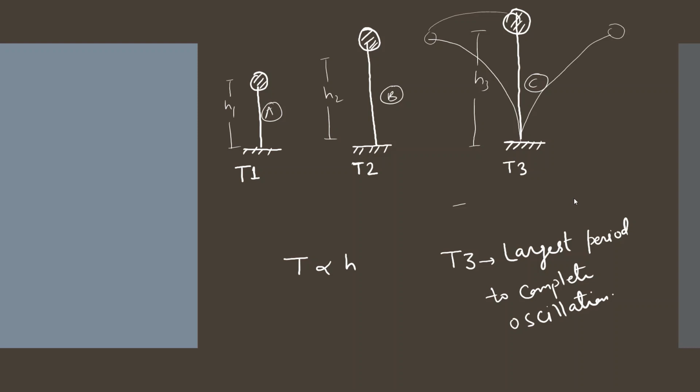So what we do here, for converting any structure, we generally have a multi degree of freedom system, but we are only focusing here on the single degree of freedom system. So we convert all the structures; suppose its time period is 2 seconds. We will assume that it is a single degree of freedom system whose time period is 2 seconds. Any structure, we will just replicate it with a single degree of freedom system, and then we'll solve the problem. That whole mass and lumping, all these.